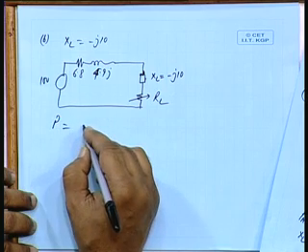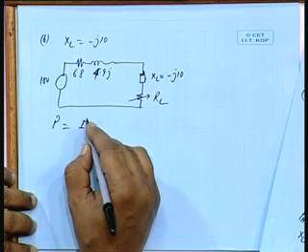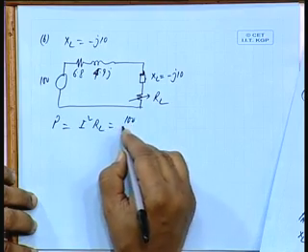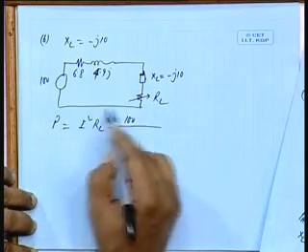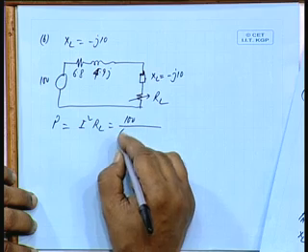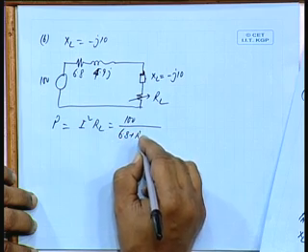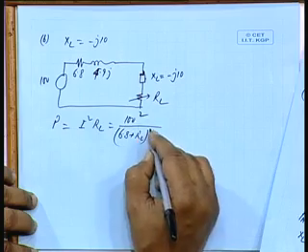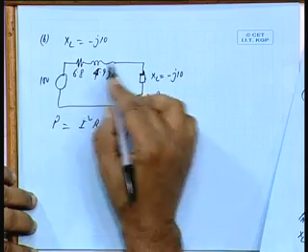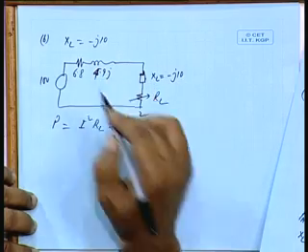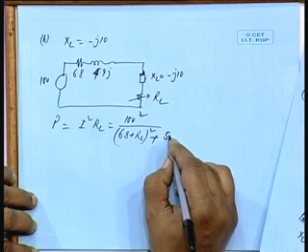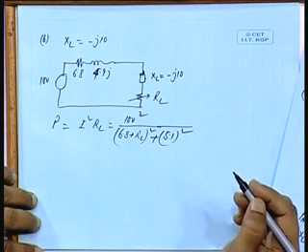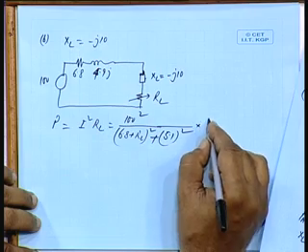P is equal to I squared RL, which means 100 divided by how much is the current? 6.8 plus RL. So, if you square it, 100 squared by this squared plus total reactance, which is minus J 10 plus 4.9, so 5.1 squared, is that all right, multiplied by RL.